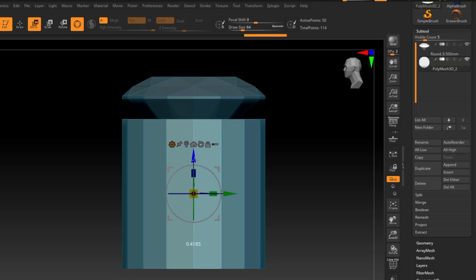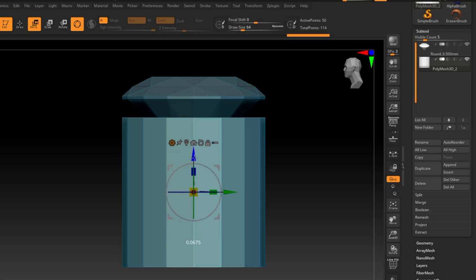So what this is going to be is it's going to be one of the rails around the basket setting. So it's going to be the rail closest to the top of the stone. Now, as far as the height of it, typically I'll aim the top of the rail to be just a hair under the distance between the girdle and the table. So look at this distance, and then look at this distance. You want this distance to be a little smaller than this.